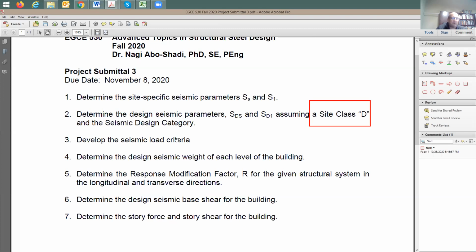As we said, when it comes to seismic weight, you're gonna include here what? Weight of the concrete deck and steel deck, steel beams, additional dead load, partition weight, 10 PSF, exterior skin. We discussed this in detail. How do you figure this out? And then if you have permanent equipment like the AC units on the rooftop, as we said, it's going to be maybe 10 kips. Am I correct about this, 10 kips? Yes, sir. It was 10 kips.